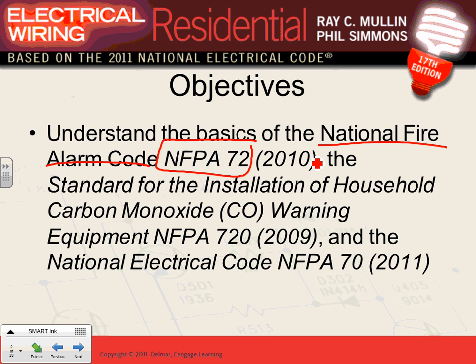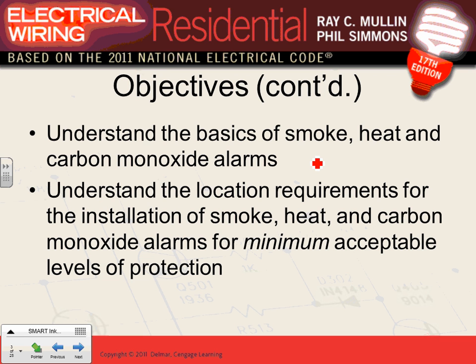And also the National Electric Code, this is our baby here. The National Electric Code says if you have to put a fire alarm system in a building, this is how you have to wire it. Cool? Can I have thumbs up, Chad? That's the 2017 NEC code book saying this building needs a fire alarm system, right? Now, what type of cable? How am I going to install this cable in the plenum ceiling? That's where the NEC code book is going to be your friend here.